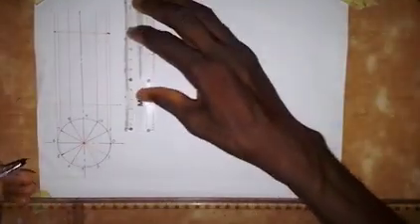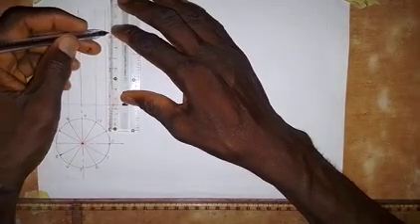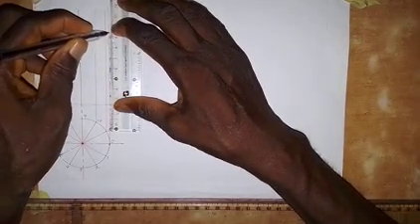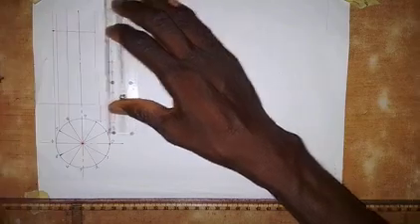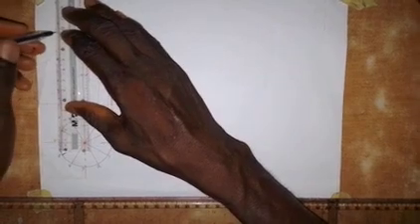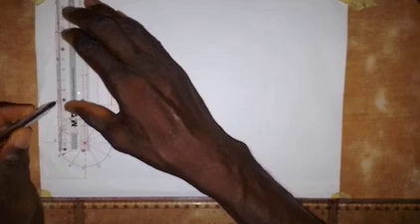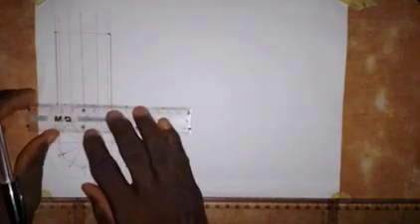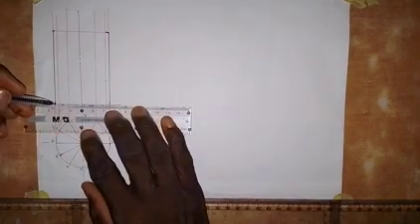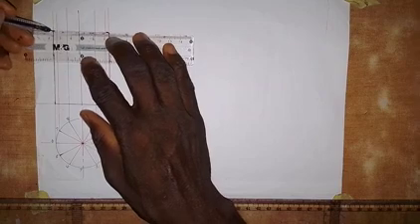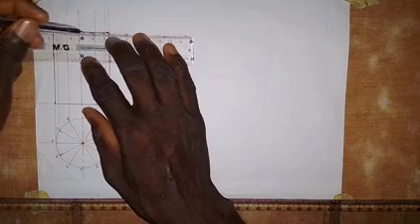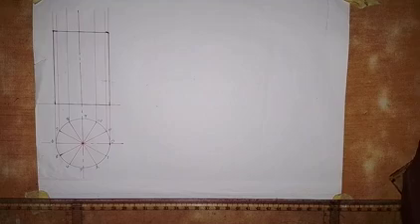Alright, so the next thing that we are going to do is to bring out the front elevation of the cylinder. Make this line a thick line from here down, and then come to this side, draw this vertical line as a thick line from here to the base. Then make this base line a thick line. And here also we make this a thick line like this. Alright, so this is the front elevation of the cylinder as you see here on the screen.